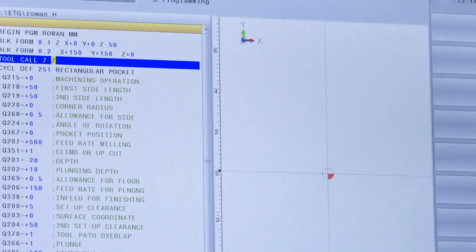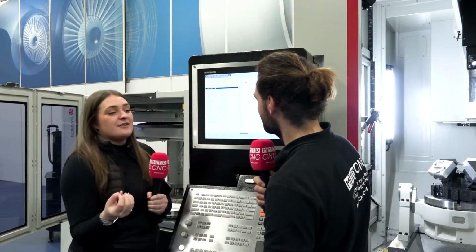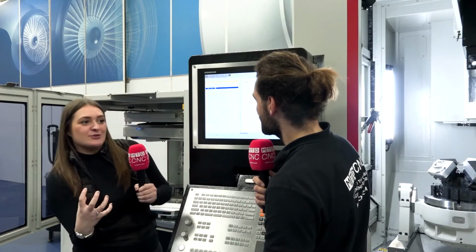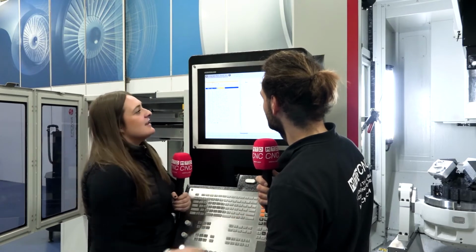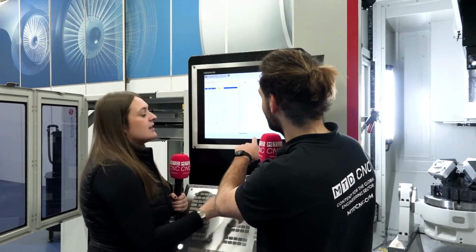Yeah. So if we click that, the tool is now going to be in the Z axis. We can change that if you have a different machine where your spindle's on the side, you can change it to X axis. So your speed, what spindle speed should we do? I don't know, 3,000. Okay. If you want, you can put in your cutting speed as well.